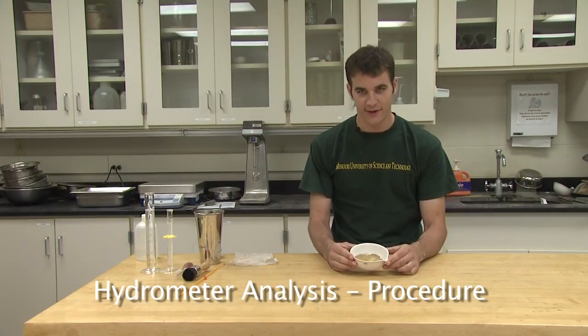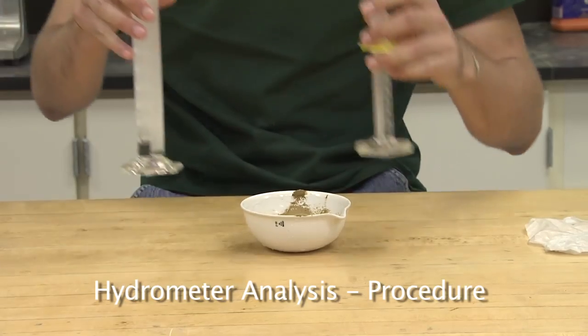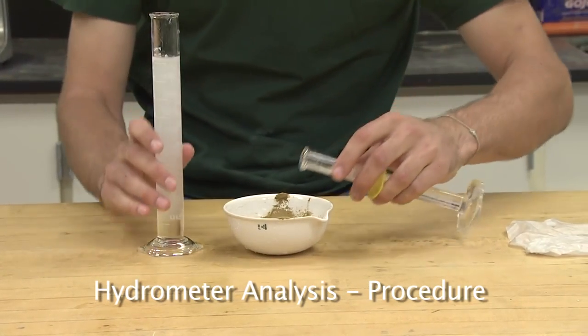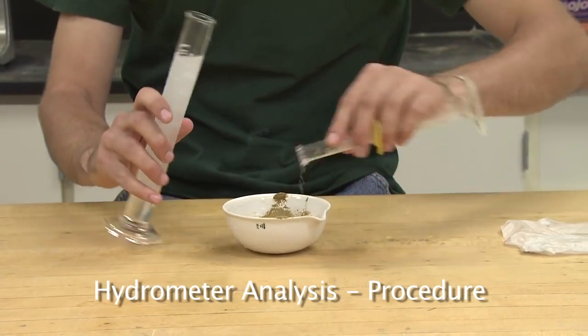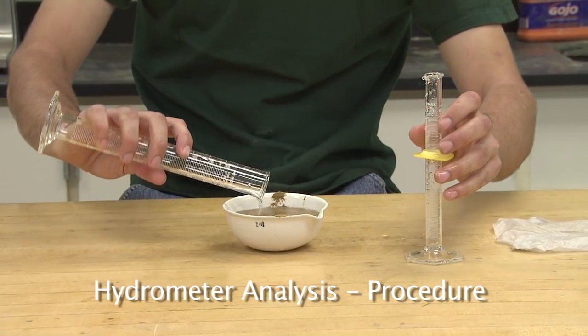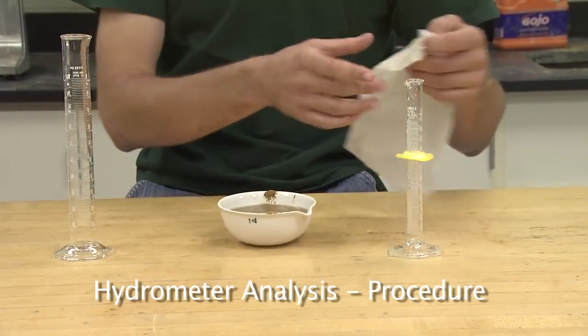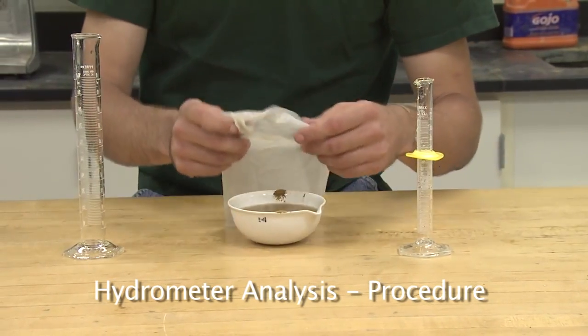In a small evaporating dish, mix the soil with 125 milliliters of 4% sodium hexametaphosphate. Cover with a wet paper towel and allow to stand for 15 minutes.